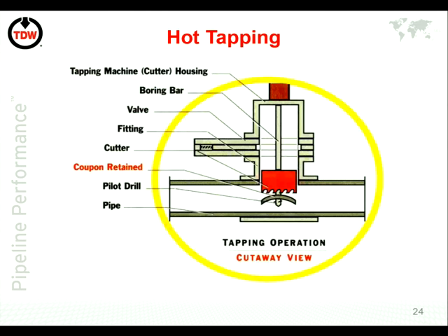So it should be properly sealed there actually when you... Yes, it is. The fitting which is welded on is the first process. It is then assembled. The machine is assembled. It's tested. It's pressure tested. It's purged before you start the drilling process. So you put your machine on the pipe here, and you purge it. Yes. You vent it. Yeah. And then you will start the drilling.